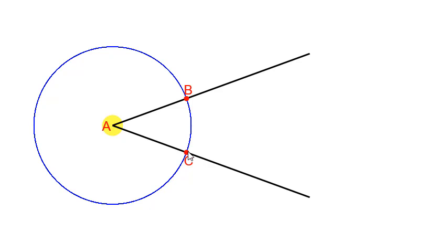We have two conditions on these circles. The first condition is that the radius of the circle around the point B is the same as the radius of the circle around the point C. So whatever you set the compass at for the first circle, keep the compass at the same setting when you draw the second circle. The second condition that we have is that the radius of our circle must be greater than half the distance between the points B and C. The reason we have this condition is that we need these two circles to intersect, so the radius must be greater than half the distance between them.